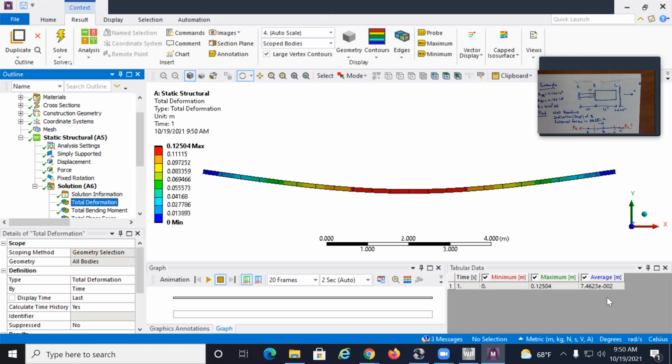As you can see, because this goes in bending, the bending moment is going to result in an axial stress or a normal stress, sigma x along the x-axis, that is equal to minus Mz over Iz times y. So this is bending axial stress. We can also call it bending normal stress.